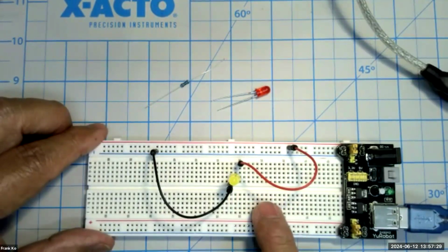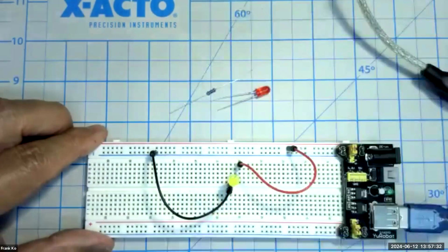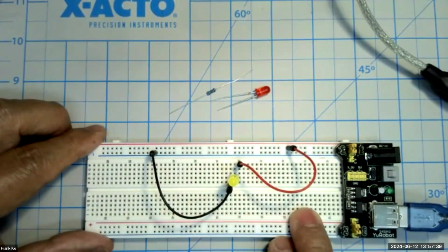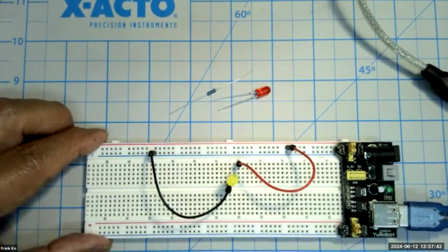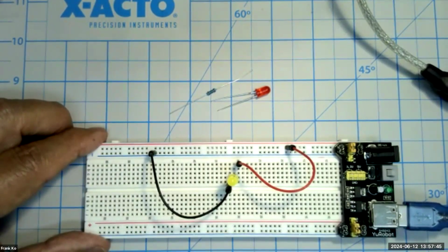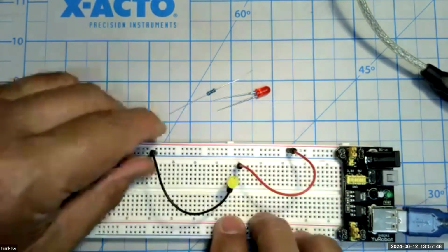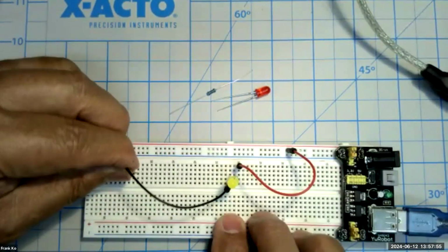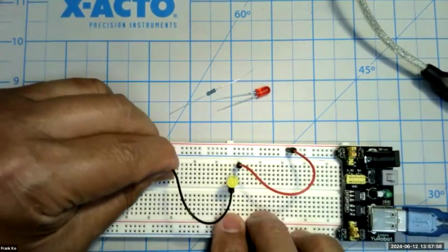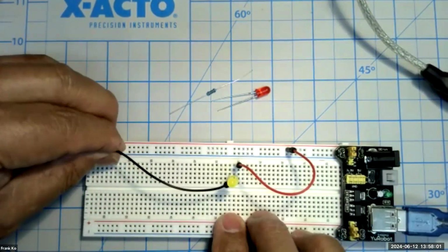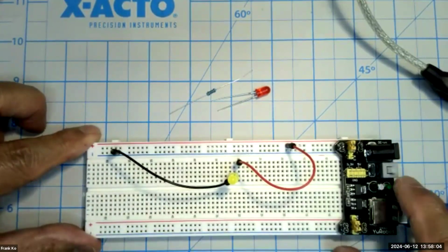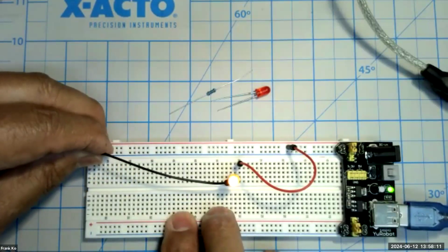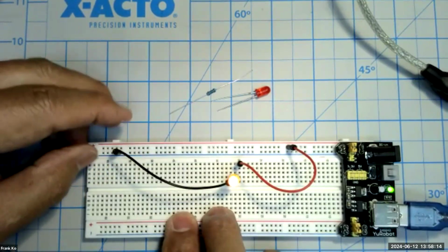Another reason why the circuit may not be lit up, separate of residue or some kind of contaminant on the wires, is that there could be some contaminants in the breadboard. Now, if you happen to run into one or two of those, it doesn't mean you've got a bad breadboard. It simply means that you've got to use your breadboard more often. The continual pulling up and down of these pins into various holes will ensure better electrical contact to your circuit. So if, for example, I have this on the blue rail and it does not light up, it lights up in this case, but let's say for a moment it doesn't, it simply means that particular contact point may have some contaminant in it.